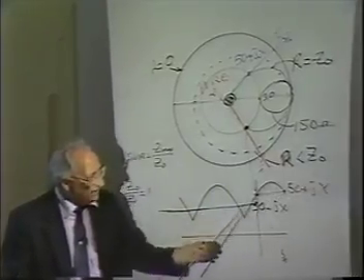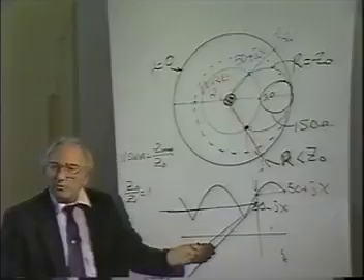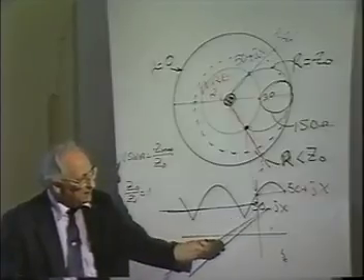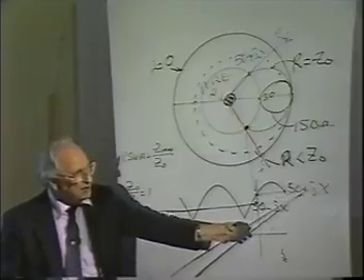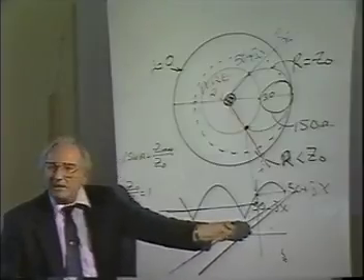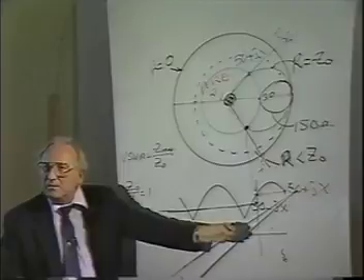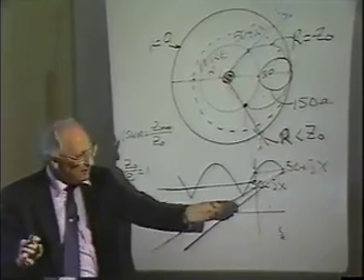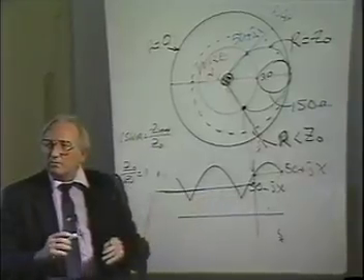But now you see you still have a pattern in here, but looking in here you wouldn't see that, would you? When you put this in here to cancel this, what you've actually done is directed all the power to be dissipated in the 50 ohms. You've redistributed the relationship of voltage to current so that all the power is lost in the 50 ohms. That's all you've done.